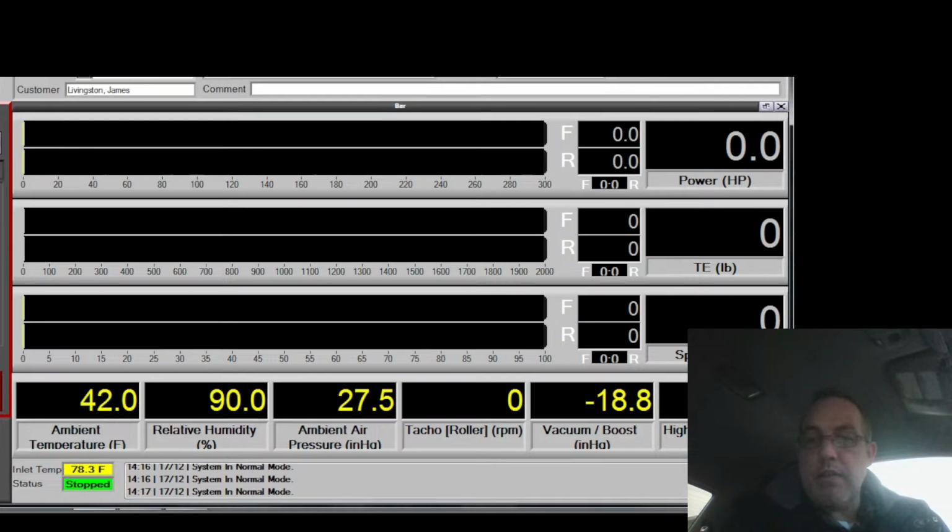Hello MK. How much better are the X2s? I don't know the answer to that. I know the X2s, I believe they flow a tiny bit more. They have very different short pulse width tables. The X1 short pulse width table, I think, is better, honestly. It's more linear, whereas the X2s go like negative 45%. Like they've got a big negative trend.